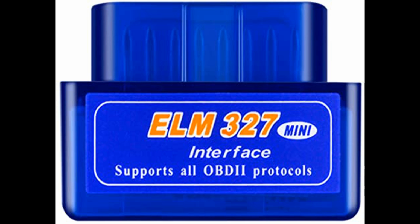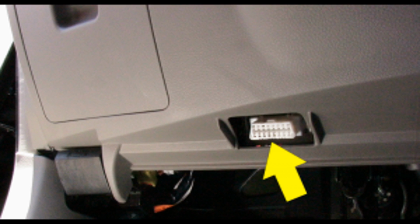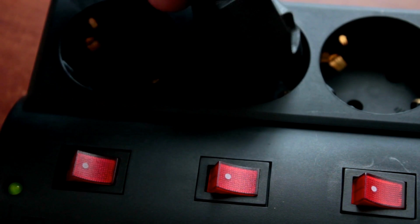So to do that, you're going to need to interface with this computer. So what can you do? You'd use what's called an OBD adapter. There's a wired one, but for me, I'm using the Bluetooth one. All these cars have what's called an OBD port, and it's pretty obvious from there. You just plug the OBD adapter in, and that allows you to interface with the car. And of course, if you're using Bluetooth, you do that over Bluetooth.